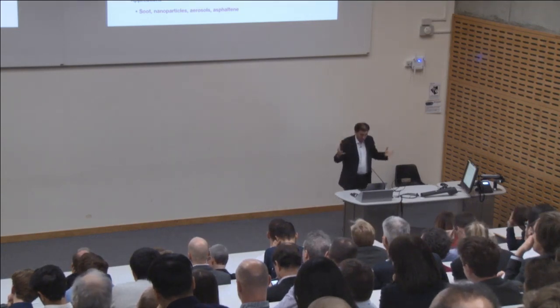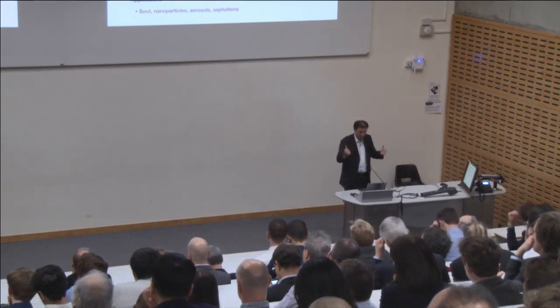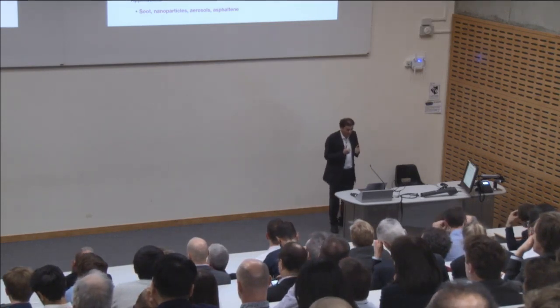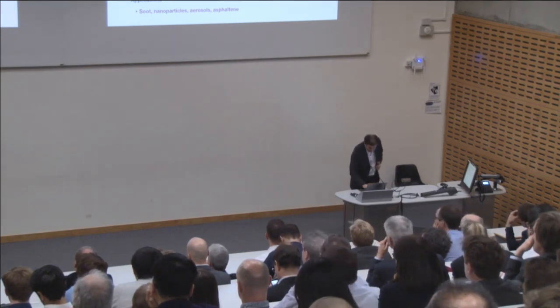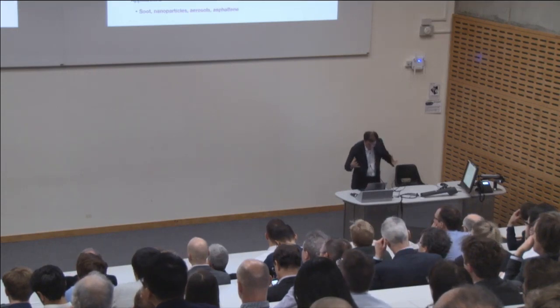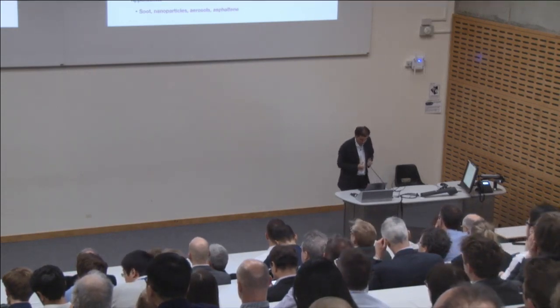But what we have done is to couple the population balance with CFD. And we've done this for RANS, LES, and even DNS recently. And we have shown that at least with these new methods that we developed, it's possible to do this. It's computationally feasible. That's one of the main messages I want to give today.